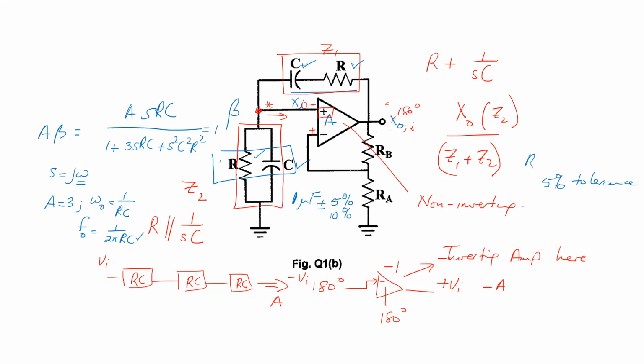Okay, same thing with the resistor. So whatever resistor value we calculate, remember that it is a 5% tolerance that you're dealing with. So the best thing to do is that you measure it, because you don't want one R plus 5% and the other one happen to be R minus 5%. Then when you put this on your breadboard and try to make it work, it's not going to, right?